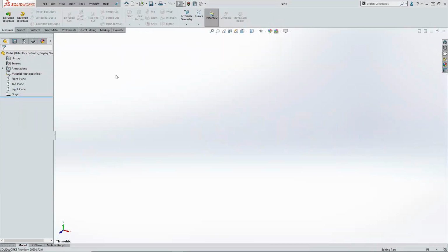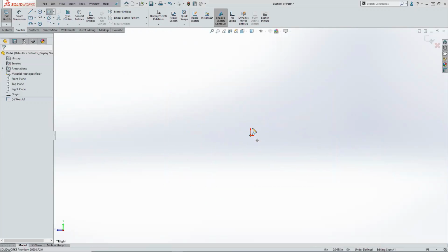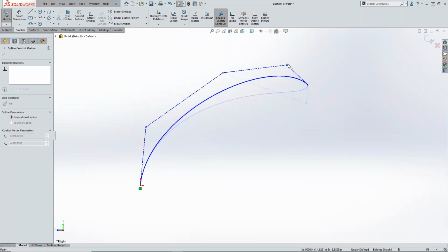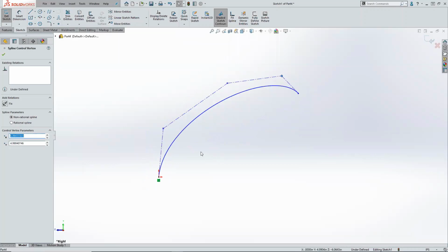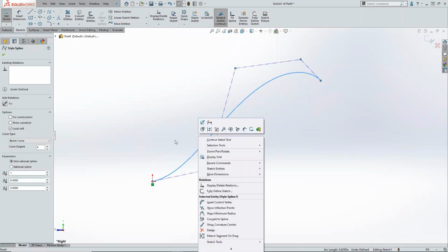Let's do a style spline. Now, a style spline is different yet again. A style spline is going to be the ideal for so many people that don't like to bother dimensioning splines, because there's no control handles. Okay, you're going to drive this strictly by these points right here. Easy enough. Notice there are no control handles. You can probably force fit them in there, but I'm not seeing it.